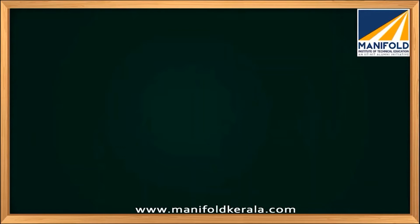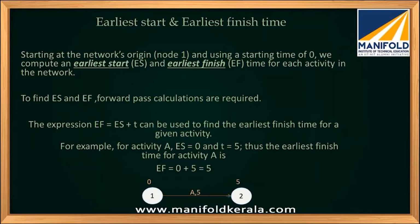So people have come up with another method to find the critical path. For that, we need to understand certain terminologies. Two of them are the earliest start and earliest finish time. Earliest start is nothing but how early an activity can be started. If the activity is starting at its earliest time, the earliest start time plus the duration of the activity will give you the earliest finish time. It's very simple.